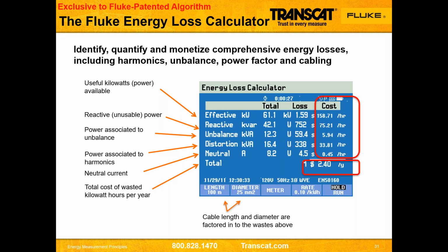So you could say I'm paying 0.0001, which would be 1 cent kilowatt hour. And that, along with the length and the diameter of the cable that's going from the control system or the motor control to the load, I can actually figure out how much IR loss I have and know how much I'm wasting. And we're going to annualize this. We're going to totalize this.